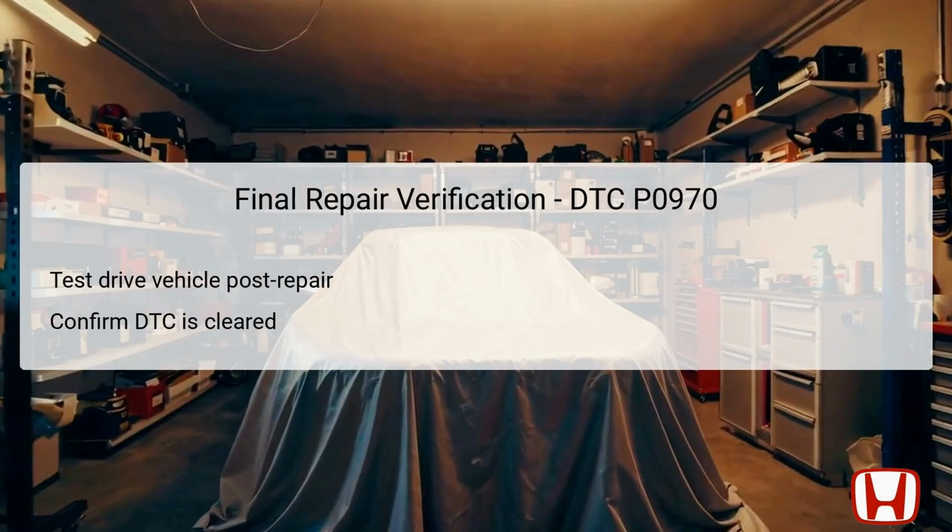Upon returning to the service area, a final scan using the Honda Diagnostic System, HDS, should be performed to ensure that the diagnostic trouble code is cleared and that no new codes have appeared. This step protects against resuming operation with unresolved issues, thereby ensuring the vehicle's overall reliability and performance.